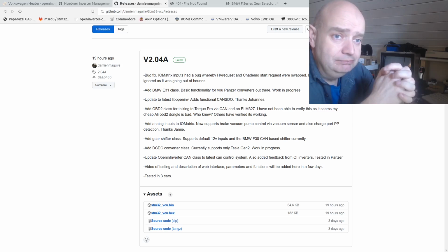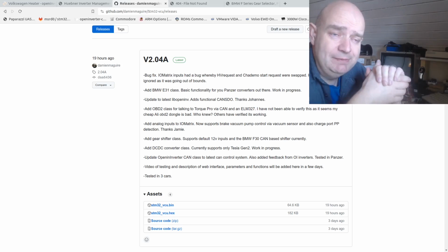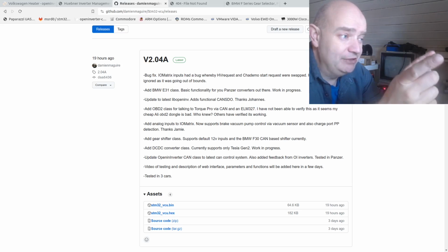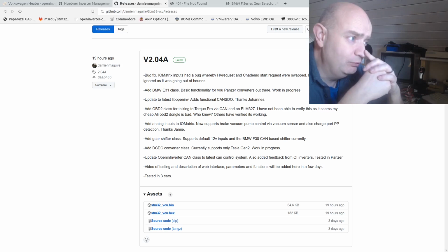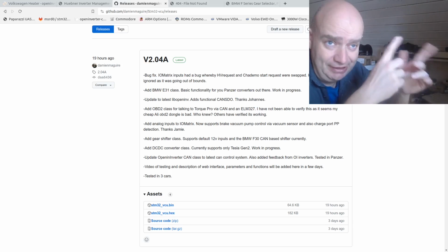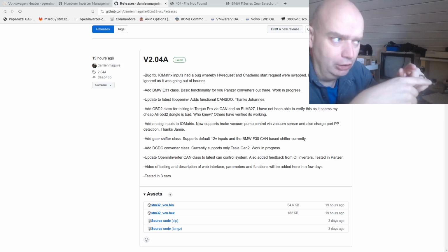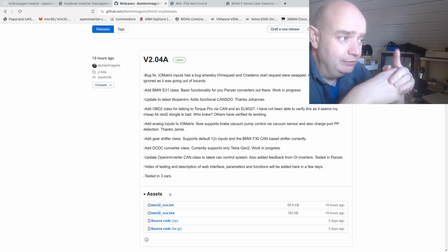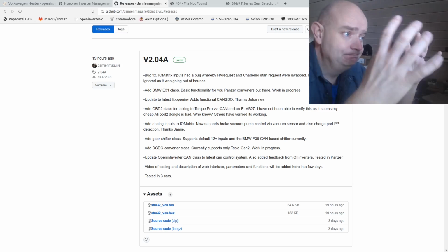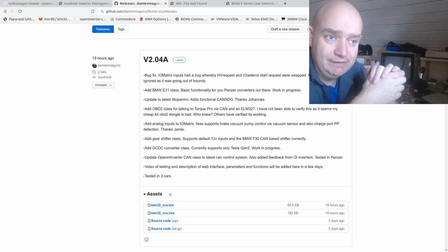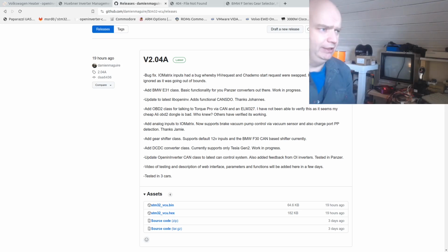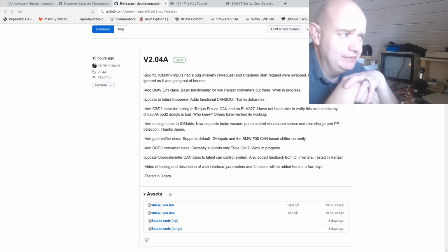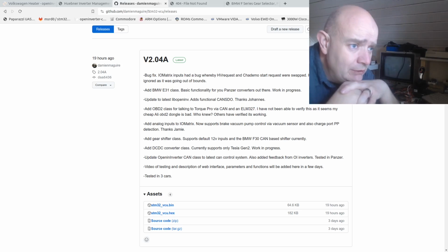And there's another kind of HV request, designed for CHAdeMO fast charging, and that was actually swapped with the AC charging HV request, and the AC charging HV request was not functioning at all because it was out of bounds of the array that was defining these pins. So it took quite a bit of finding for my brilliant software skills to detect that, obviously, but I got that fixed.